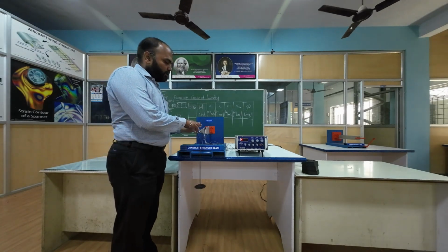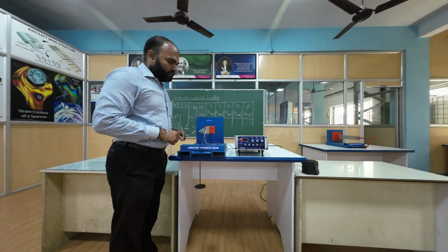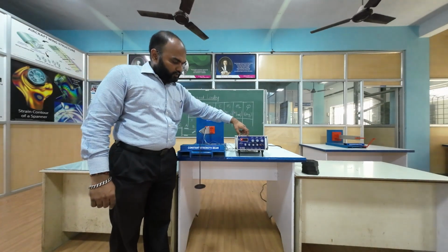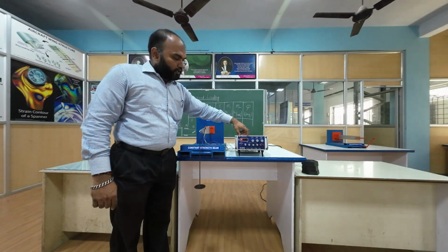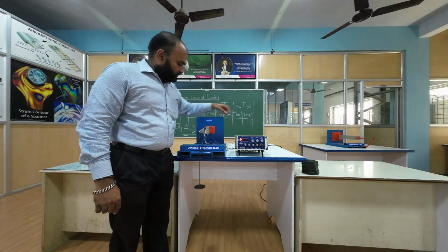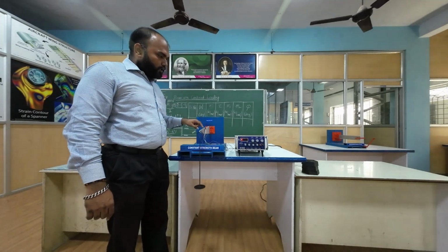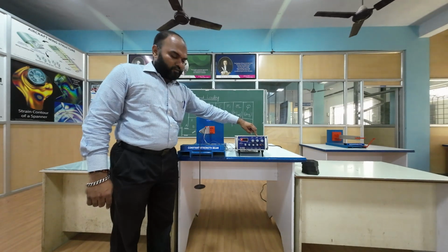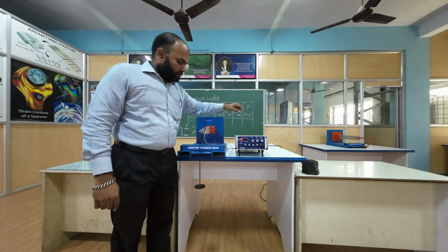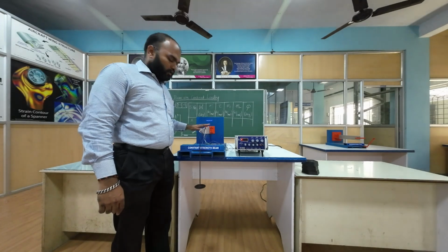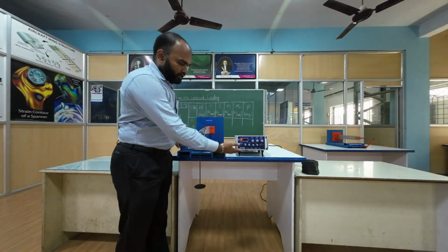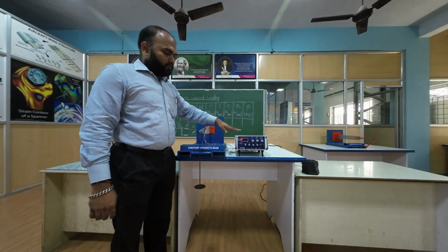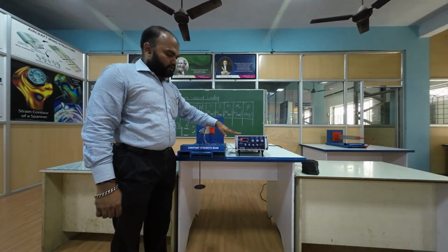The corresponding wires are connected to the digital indicator, where you have your display. Here you can see the strain values. You have a channel selector for selecting which strain gauge you want to take data from. Then we have the bridge selector: quarter bridge, half bridge and full bridge. Here we are using half bridge for all the strain gauges. Then we have coarse balancing and fine balancing, so you can set zero before starting the experiments.